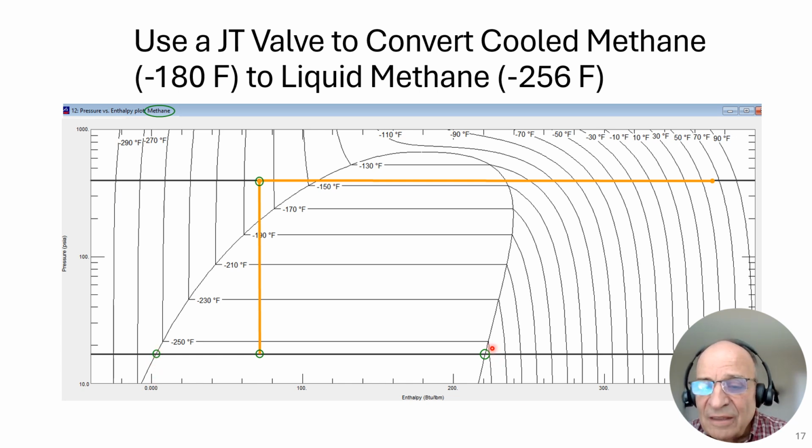And this is vapor, saturated vapor methane. Now, what do I do with this saturated vapor? Well, I really cannot store it, so I'll extract the refrigeration that's available by transferring heat to it. I can transfer heat from this stream to this fluid. Let's say this goes out and heats up to here. Well, I can be removing heat from here to here in that process, and this vapor becomes what's called flash